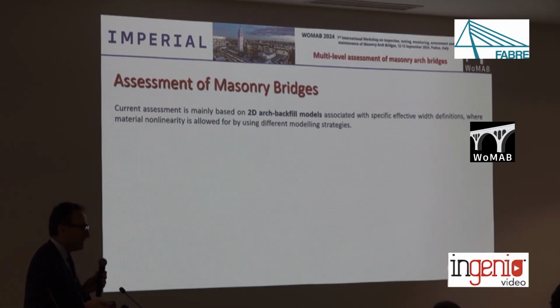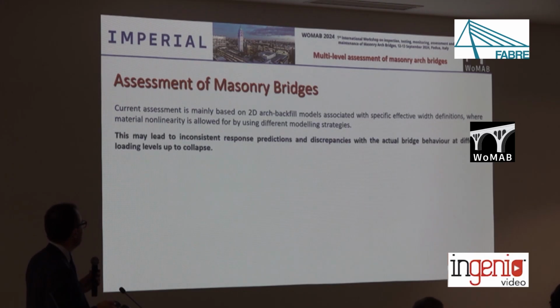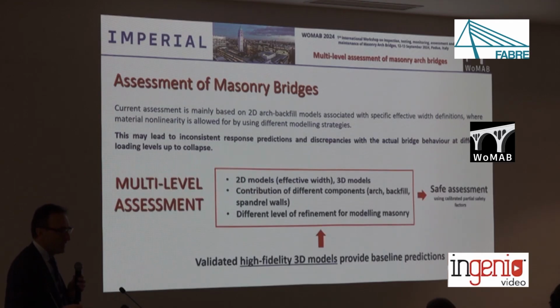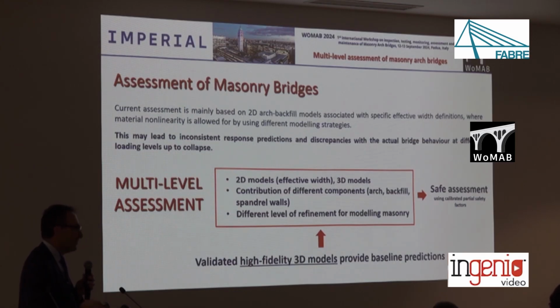And these methods consider simplistic 2D representations of the arch backfill interactions, and use different models to take into account material nonlinearity in masonry. We found that this may lead to inconsistent results, and in many cases also may lead to unsafe predictions. So for this reason, there is a need of developing a multi-level assessment method where simplistic approaches are categorically safe.